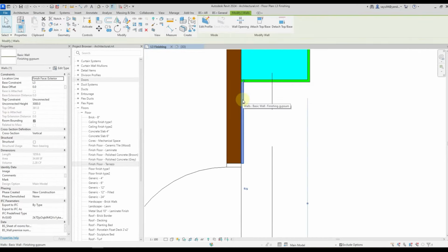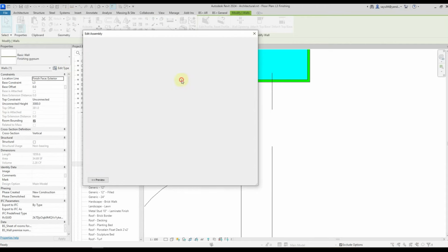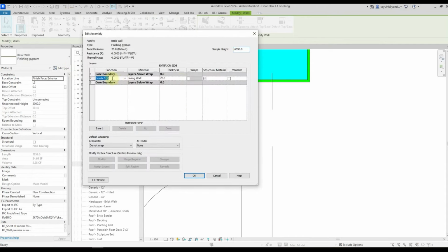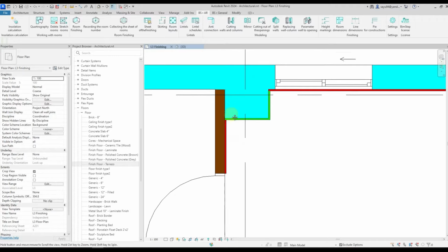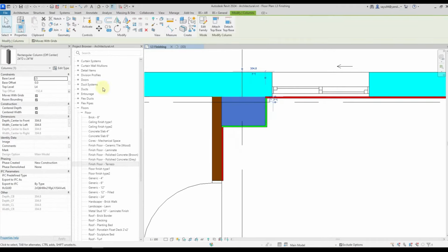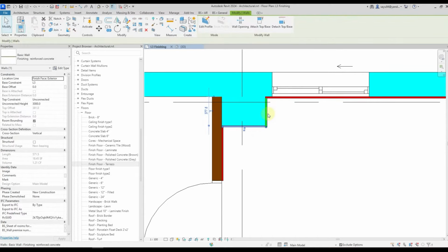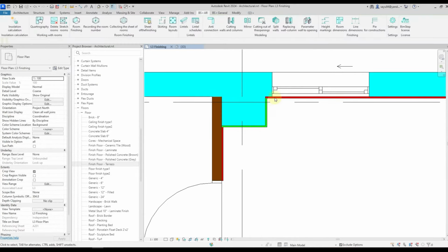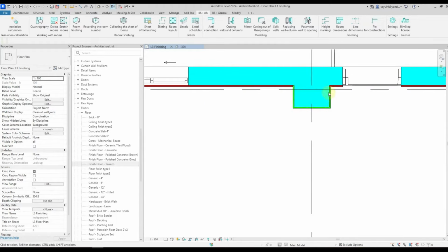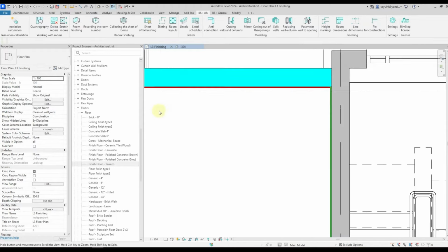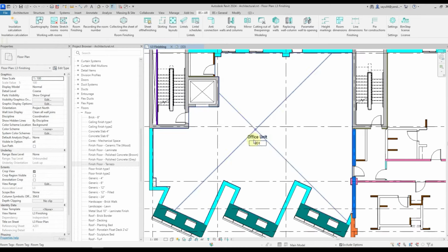I would like to draw your attention to the fact that in the type of the walls here should be set exactly finish, so that this finishing wall would not be inside the other layers. At this point we see that it's reinforced concrete and it's finished exactly in green. Next comes the drywall in red, column in green, drywall in red, column in green, and so on.